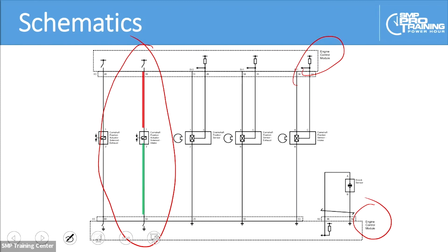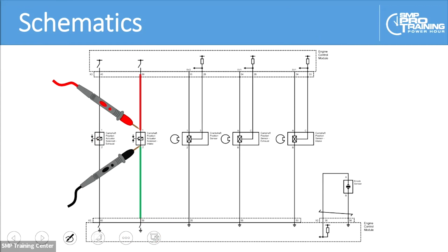And so in our diagnosis, we want to see, is a signal getting to the solenoid from the ECM. So our technician is going to connect his graphing meter to the solenoid circuits. He's going to back probe the solenoid, and so he'll actually see what's happening with the solenoid connected, and with the engine running, we're going to see what happens.